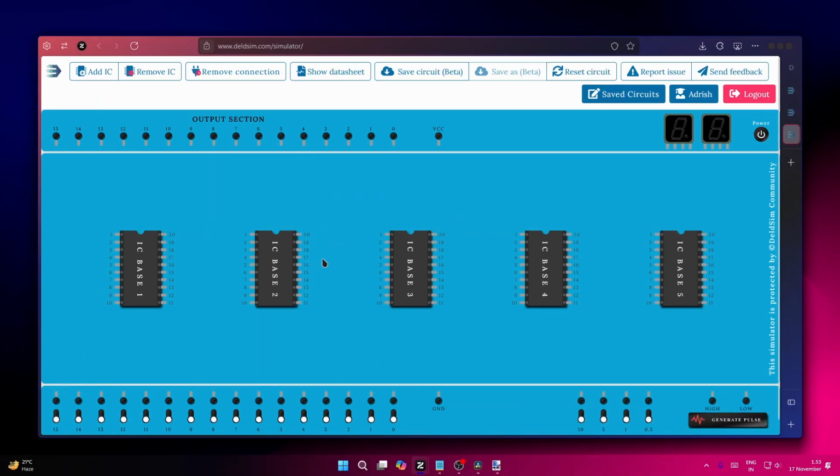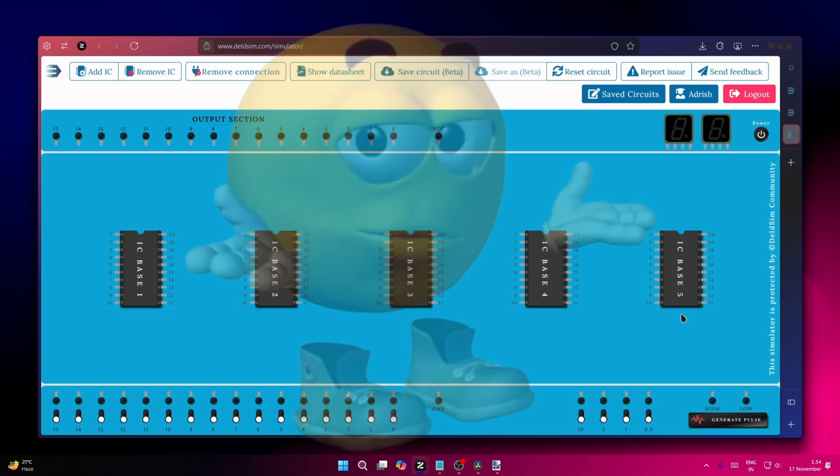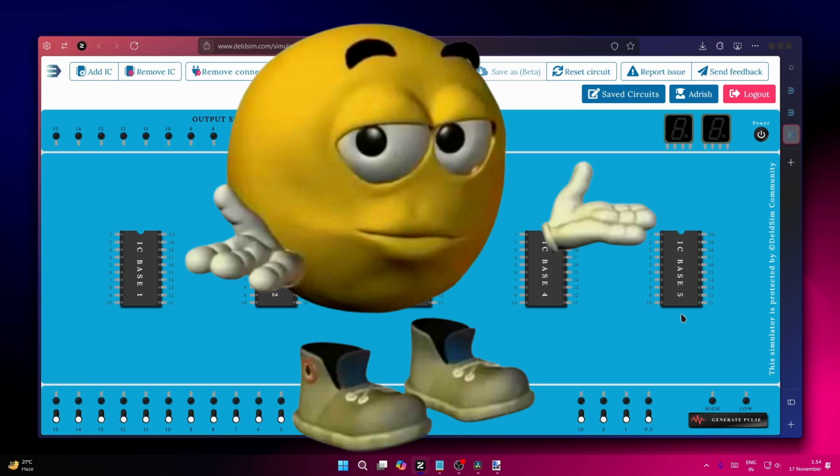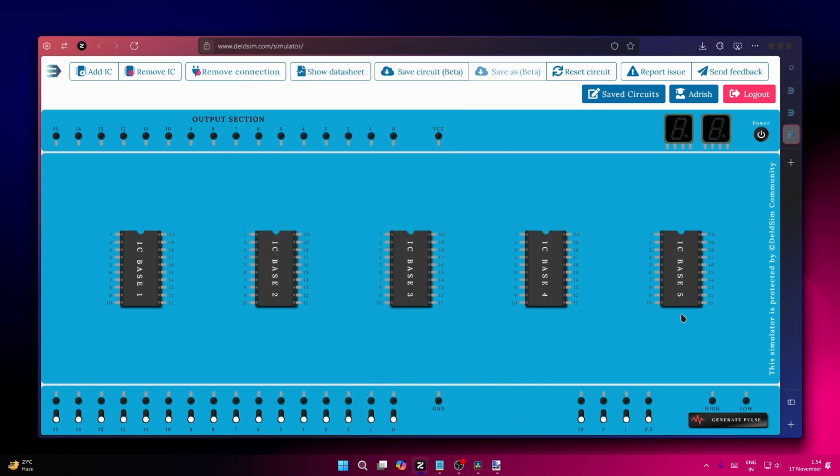And in between these things, these 5 components are what's called ICs, and this is what we will mostly be working with. Now, there are a few basic gates like NOT, AND, OR, XOR, NAND, etc. And an IC is basically just a gate, or more accurately in this scenario, 4 gates. Whoever was making these ICs thought that adding only one gate would be a huge waste of space in this big component. So they added room for 3 more. Well, it generally alters depending on the IC, but usually it's 4 gates of one kind.